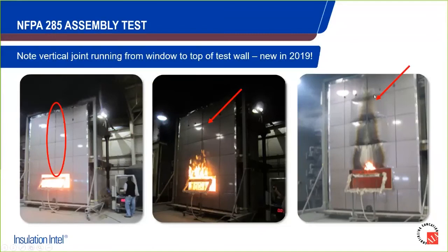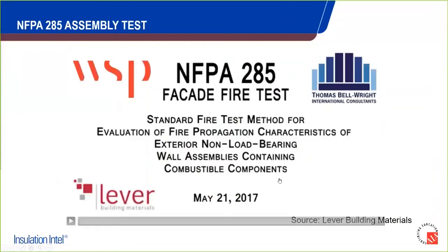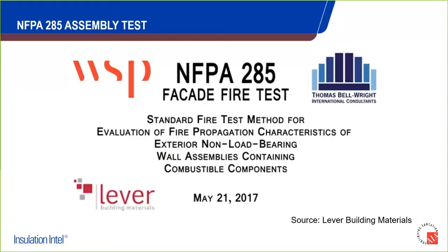This looks like a metal panel system being tested, and you see the results here and the height. Somewhere in that photo, there's a 10-foot mark, and the flames cannot have extended above that 10-foot mark. So let's take a look at a time-lapse video of a full NFPA 285 test, which lasts approximately 35 minutes. I think it's misquoted inside the video, or perhaps it changed. There's 5 minutes at the interior, then an additional 30 minutes at the exterior.